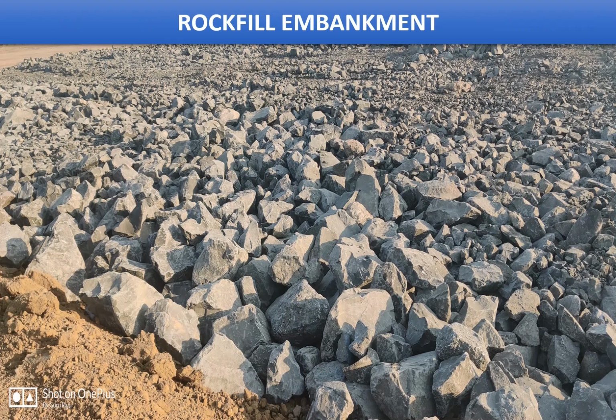If you see the picture of a rockfill embankment, to start with, it starts with these particles, where it generally needs to be ensured that the size of the particle is less than 300 millimeters, and then after laying it, you will have to fill it with the fragment particles, which are 125 mm, and then it is rolled properly to get the proper interlocking of aggregates.